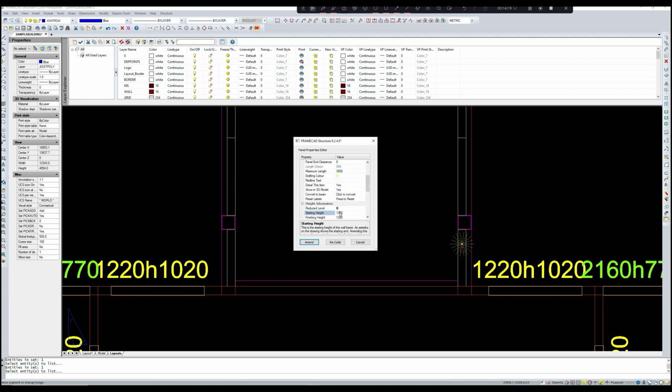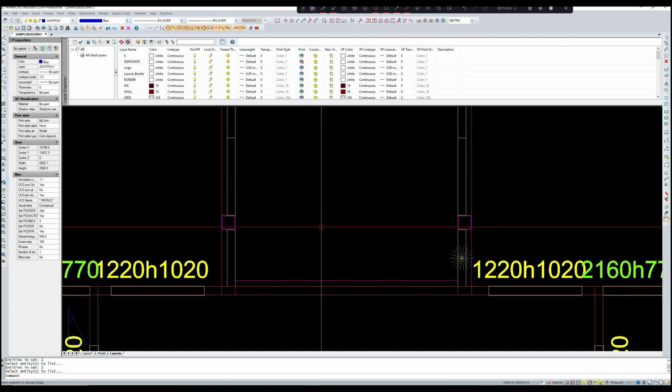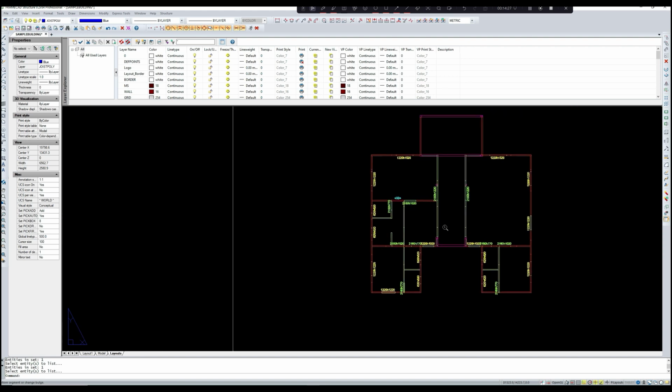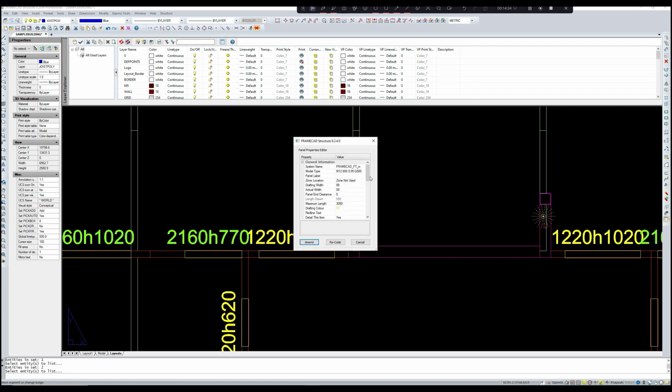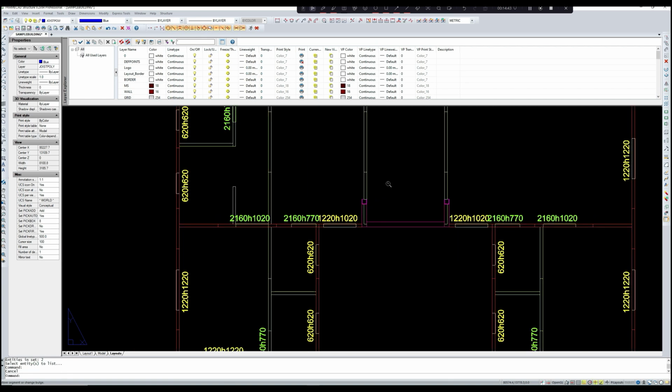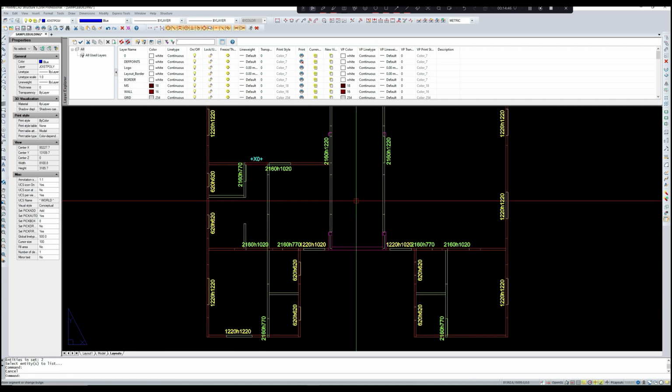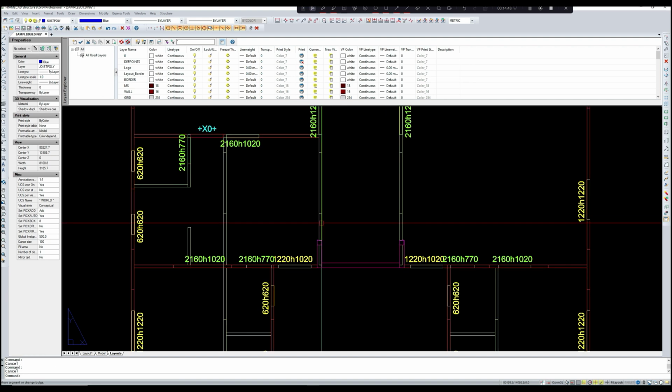No, 1384. I mean this is actually ground floor level. We should have changed the wall height. List here. List. So this should be 1300 at first floor level. Amend. So these walls all will have a height of 3050.